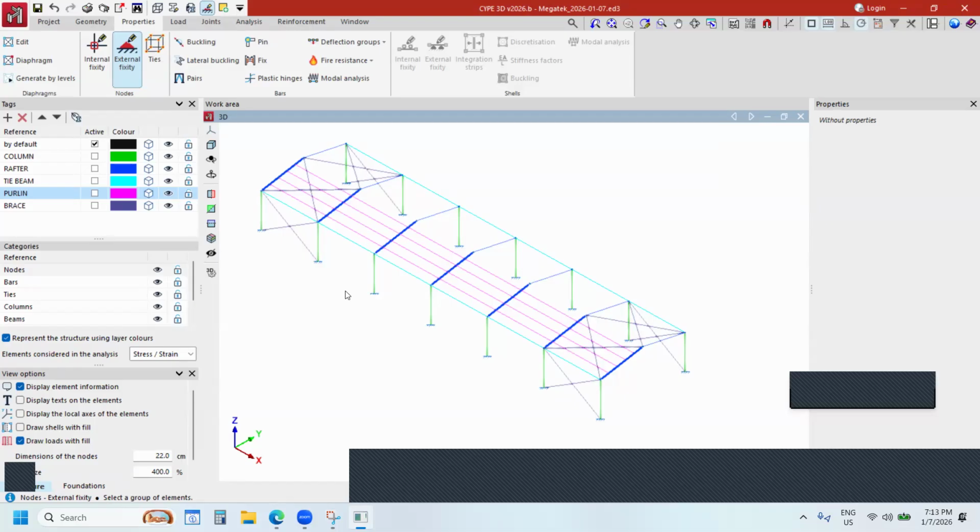If you have the shear connection, you can completely release the moments. If you have the rigid, you don't need to do anything, by default in every software. You have the rigid connectivity between the members. But if you want to simplify it, here you have the pin ends. If you click on pin, here you have the individual or multiple selection.